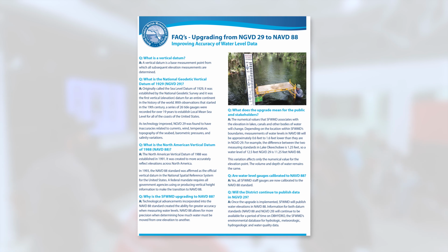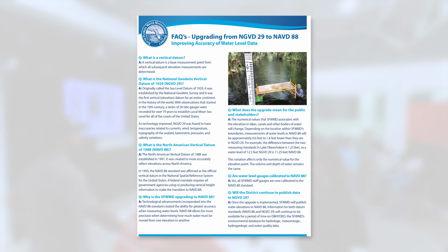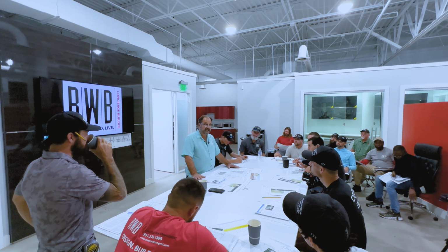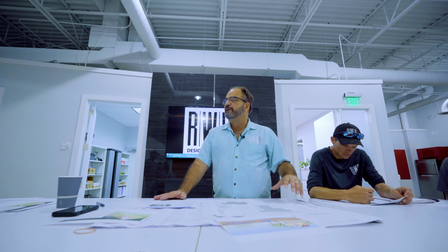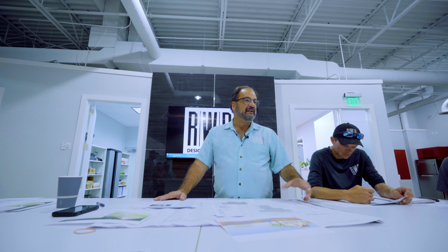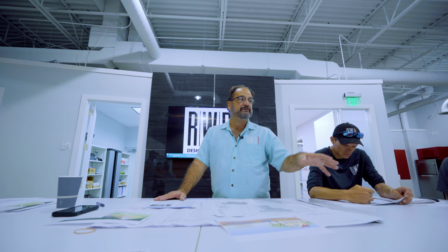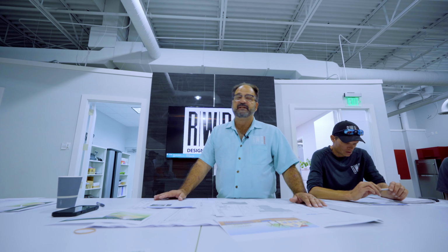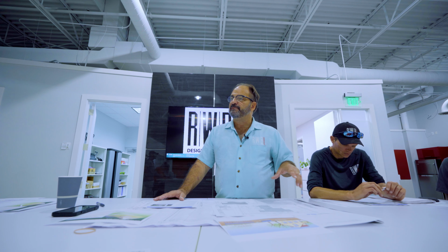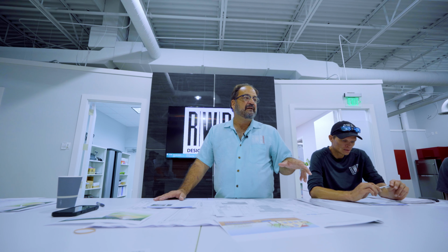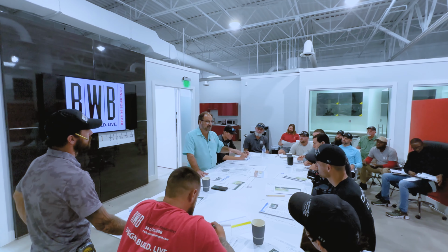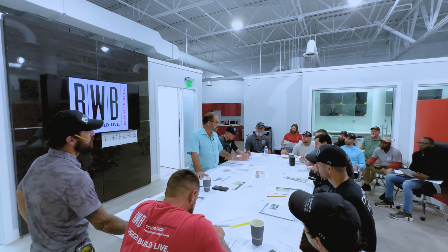Because what you're going to do is you're going to take that elevation mark and you're going to measure down or you're going to measure up. Usually when the surveyor comes in and he measures all this, I ask him to give me 2 or 3 points around the property. Because when the guy is going to lay out everything later, which we'll get into when we get the structural, he's going to need a point of reference. If we have multiple points around the property through a laser, he can take that point and transfer it anywhere. Everybody has to be working off the same point.